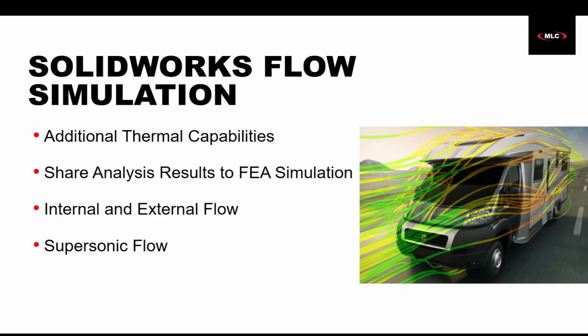This has more accurate thermal capabilities in some situations than what the SOLIDWORKS simulation can do, because this allows for airflow, convection, conduction, all that stuff. Additionally, we can actually pull results from FEA simulation. Say we do have movement or a thermal load of a part. We can actually pull that into our flow simulation, and we can use that to aid our analysis and get more accurate results.